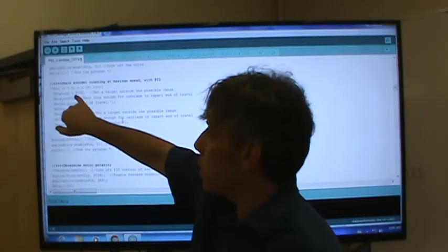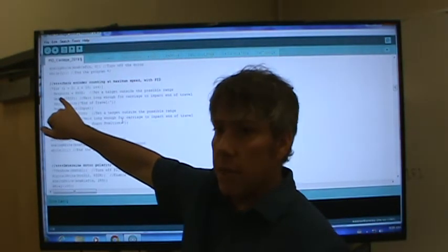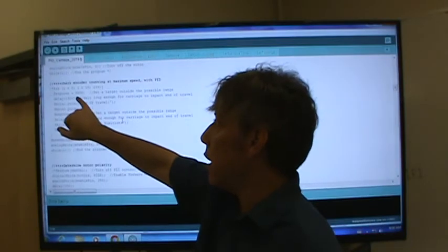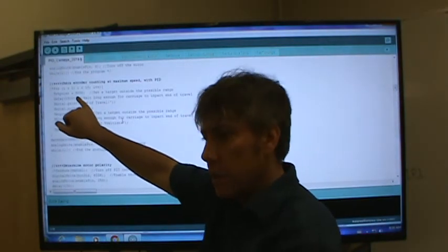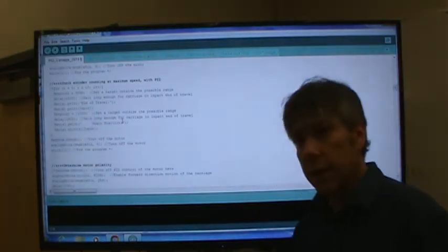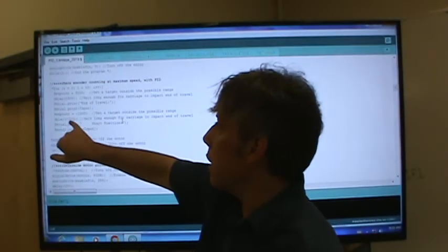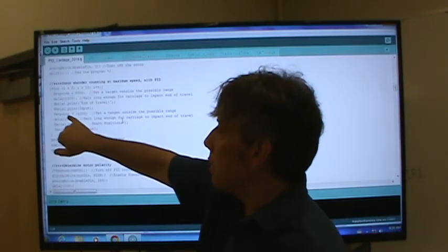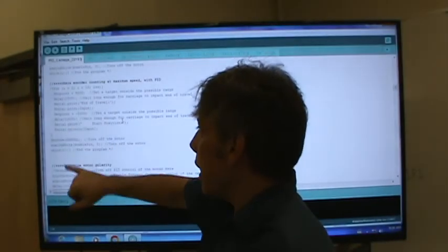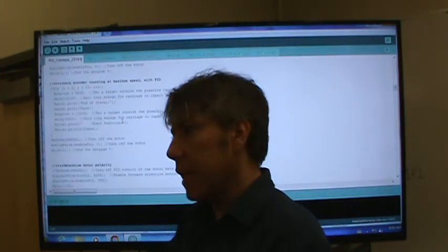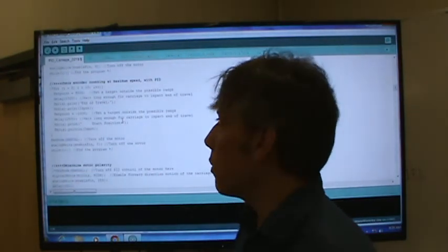So you'll see here, instead of turning the motor on, I just leave the PID loop enabled and set a target, a set point of 8,000, which is beyond the length of the carriage, but I just wanted to go as far as it could, hit it, and wait there for a little bit. That's what this 1.5 second delay is for. And then set the set point to -1,000, so it would go as far as possible to the other side. And then wait 1.5 seconds. So I did that 10 times also. I had it slam against each end of the carriage over and over again.